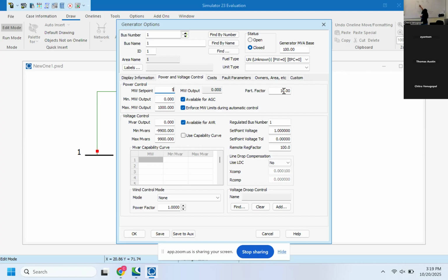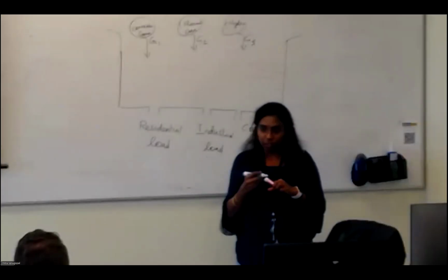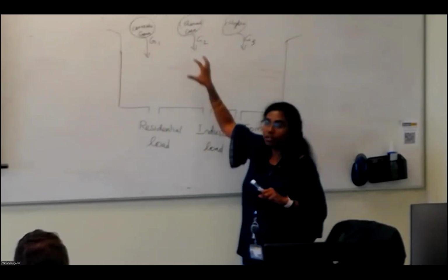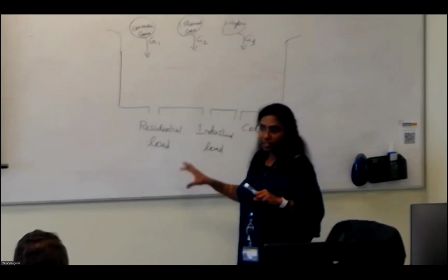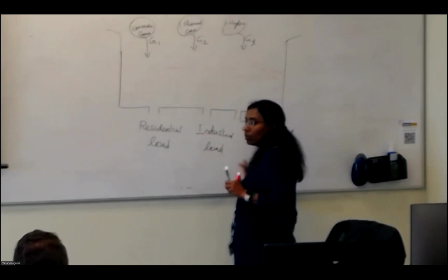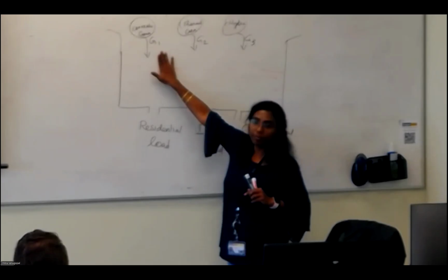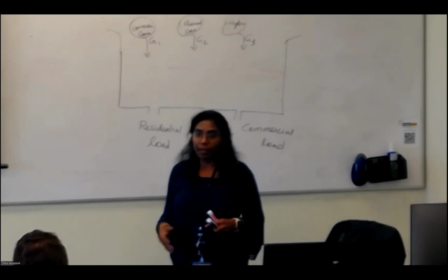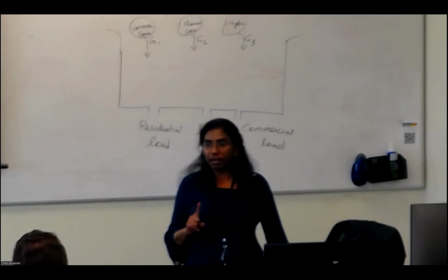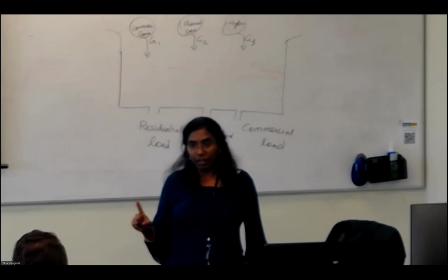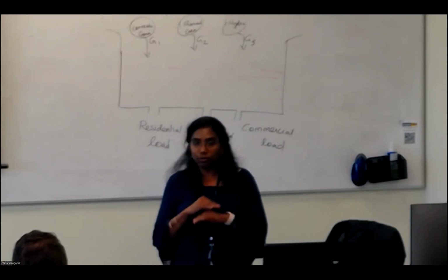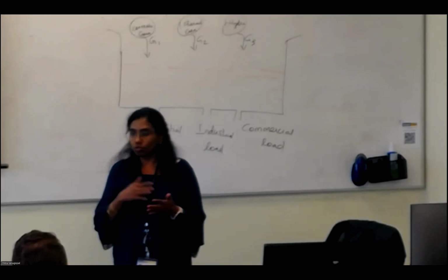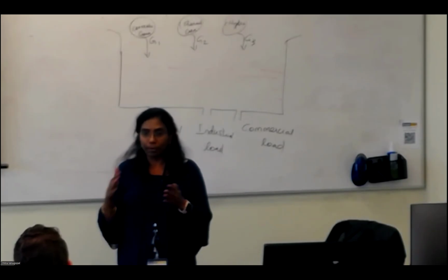Okay. So when you are connecting more than one generator to the system, we are not going to take all the power from the conventional generator or thermal generator or any other generator. To run all these loads, we have to specify how much percentage of power we need from this one and from this one, because we have to utilize all the generators. Starting a generator from scratch is a costly process and it takes time. So we cannot let any generator stop completely, because that is what we call a black start. There are so many terms related to start: black start, brown start, all those things.